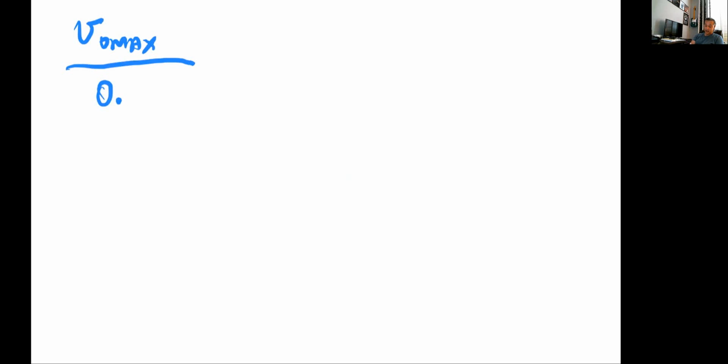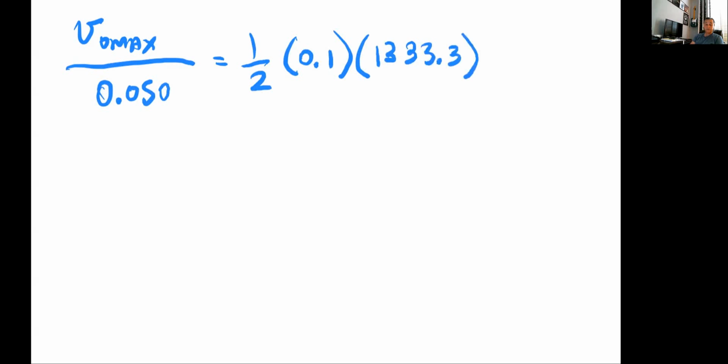So in kilo ohms, RL is 0.05, or 50 ohms. This is K prime. We had calculated the electrical width to length ratio of the channel for the P channel as 133.3, times 2.5. So all that inside the square part reduces to this.